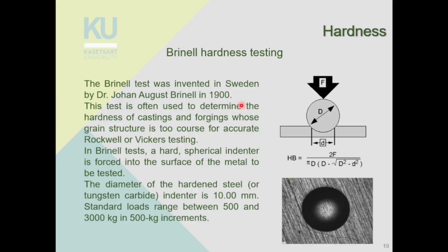All right. So, for example, Brinell hardness test. The Brinell hardness test is quite an old technique that was invented a long time ago in Sweden by Dr. August Brinell. Basically, you take a ball bearing with a known diameter. You harden the ball bearing, and you push the ball bearing onto the surface. Usually, the diameter of the steel ball bearing is about 10 millimeters. So basically, you have this bigger D diameter of 10 millimeter.